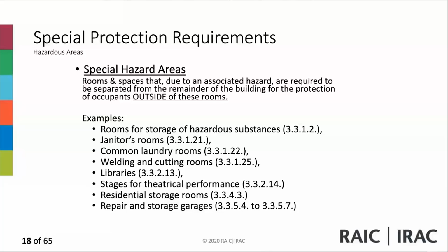In a building more than 3 stories in building height, and whether it's a Group A, Division 2, 3, 4, or Group C occupancy, if it's more than 3 stories, you require a vestibule. So that's a plus to the separation requirement. And also there are provisions for ventilation and vestibule dimensions. That's in Article 3.3.5.7.(4).